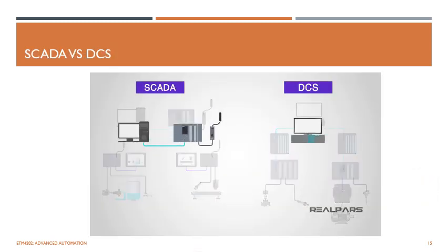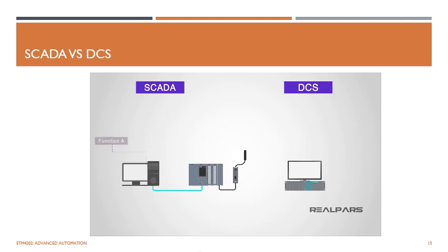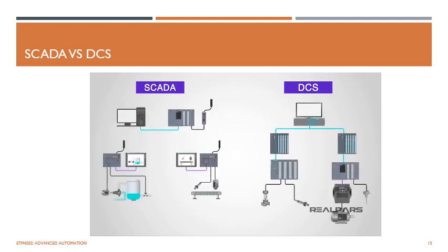So let's take a look at the difference between a SCADA and a DCS system from this video. In the earlier days, DCS implementation was more cumbersome, while this DCS had many predefined functions that could be customized and deployed for various applications. This didn't eliminate the need to write code. However, it did help to facilitate faster integration because less time would be spent writing code for commonly used functions. Processing times are somewhat slower in the DCS versus the PLC RTU SCADA environment. While this is not necessarily problematic, it could have an impact on processes that are very time-sensitive.